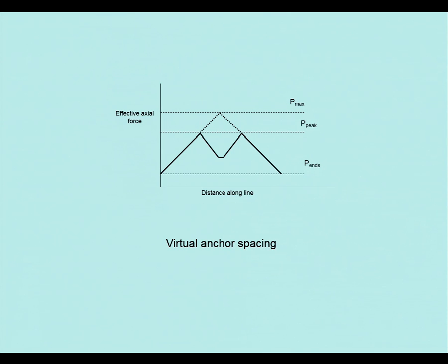So what we've done is we've made the pipe rather square, and then when the temperatures come on, it's designed so it goes up but sideways, and then it takes up a deflected engineered shape, so the force has gone out of it, so it doesn't buckle.